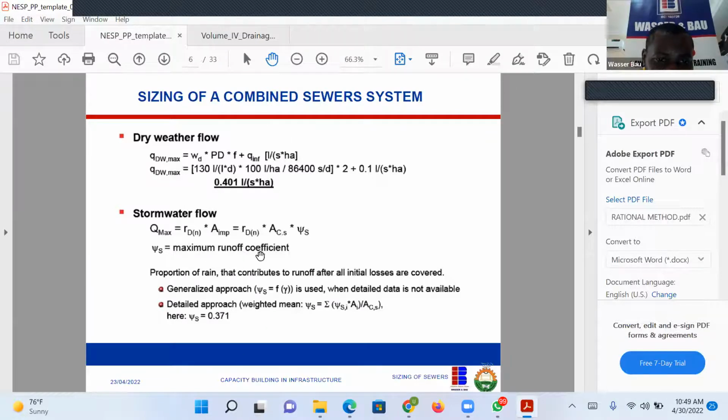So I just wanted to take a look at this. You can see that this is the rainfall value multiplied by the area of catchment, which will give you this. For me to get this, I now have to take the average, because I need the average to start multiplying with every subcatchment.